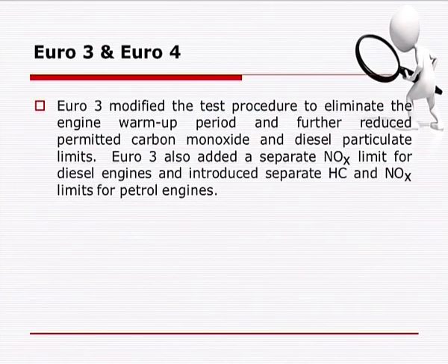Euro 3 brought another revision. Euro 3 modified the test procedure to eliminate the engine warm-up period and further reduced permitted carbon monoxide and diesel particulate limits. Euro 3 also added a separate NOx limit. They gave a new limit for oxides of nitrogen for diesel engines and introduced separate hydrocarbon and oxides of nitrogen limits for petrol engines.